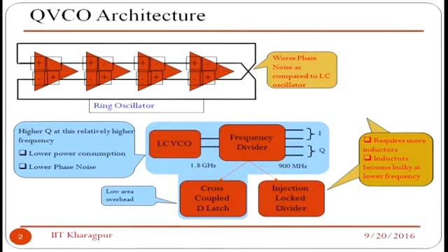So I'd say that this is the phase noise performance in this kind of ring oscillator, whereas in the case of the LC-VCO you will have better phase noise performance. Another point is that suppose you want to design an RF front end for 2.4 gigahertz, then it is better to make your VCO 2 times that frequency. Suppose it is 950 megahertz for your GSM phone, so your requirement is actually a 1.9 gigahertz kind of VCO. Why? I will explain later on. So twice the RF in frequency is the requirement for your VCO.